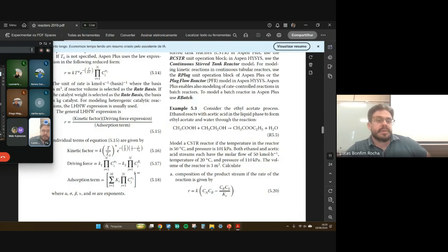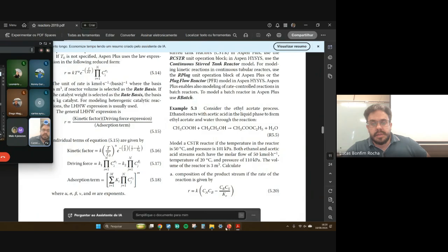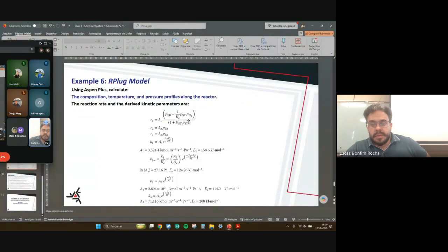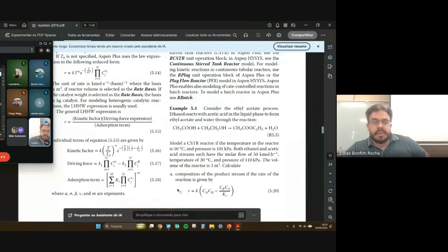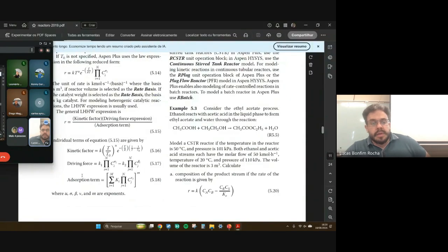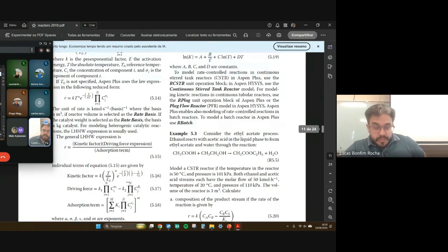And also a general exponent for all these terms, which normally we consider as 1. In our case, it is 1, but we must configure it and define this value in the simulation. When you select this model for reaction 1, these parameters for the adsorption term will appear.